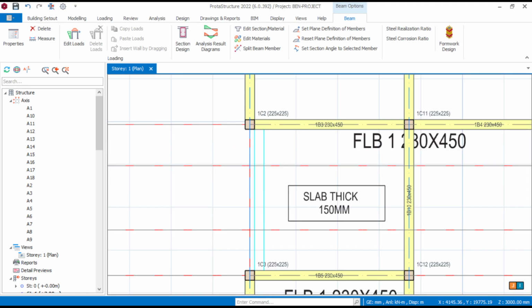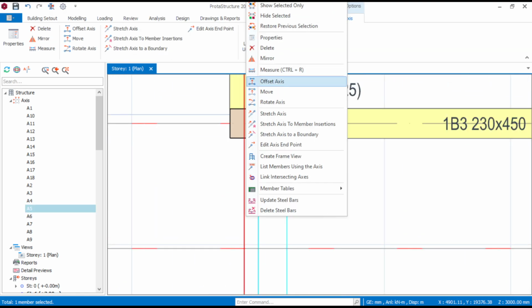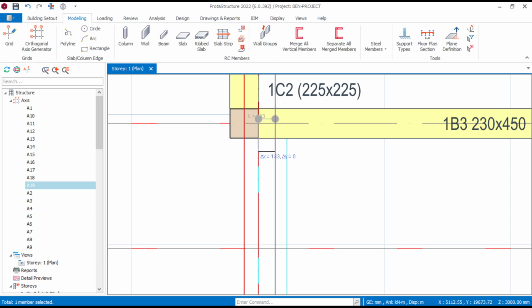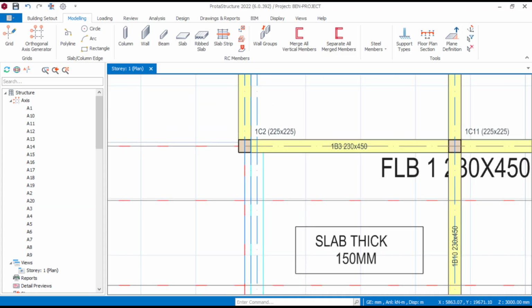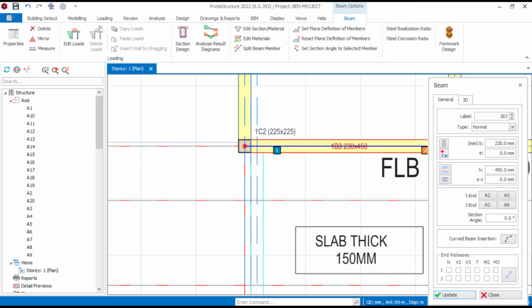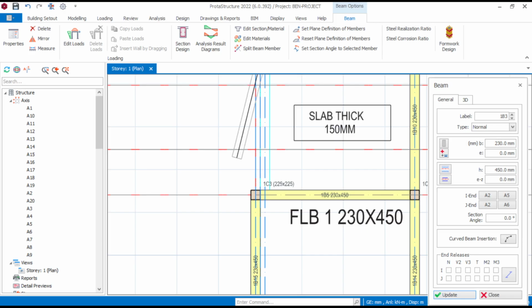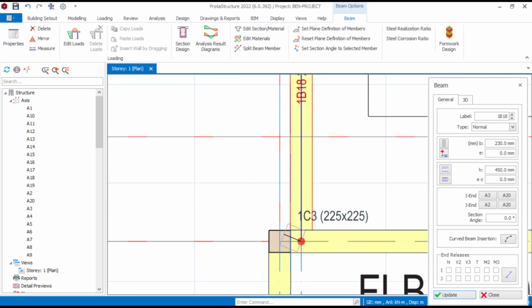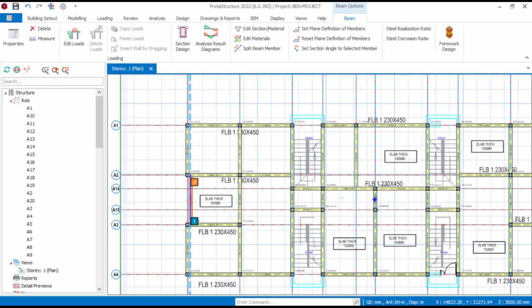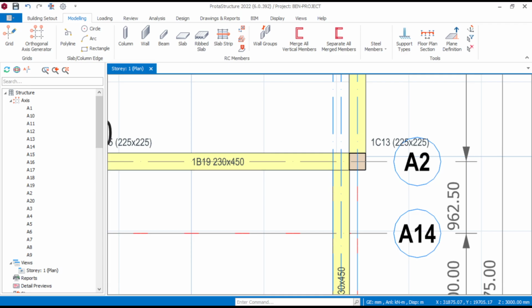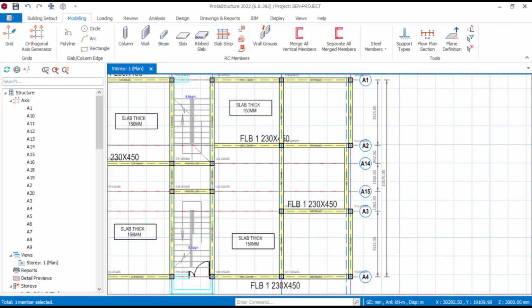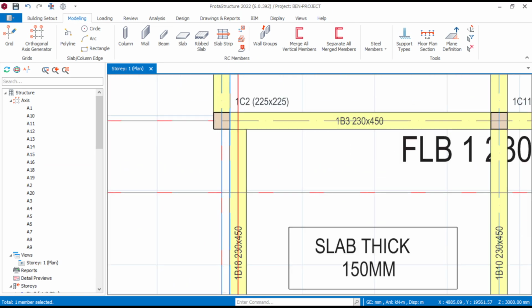Okay, so let's come to this now. The same thing we did. We'll click on offset, drop it here, click on shift F2, 112.5, then place it, enter. Are we together? Let's click on properties and let's drop this here. Very, very good. Can you see that we are almost through with our beam? So this is not needed. That was just done to get our center line.